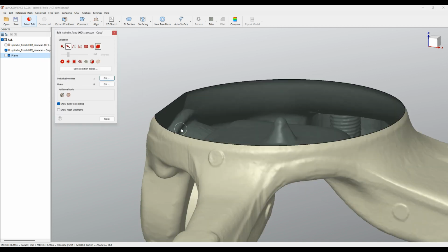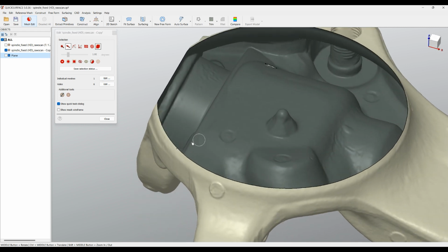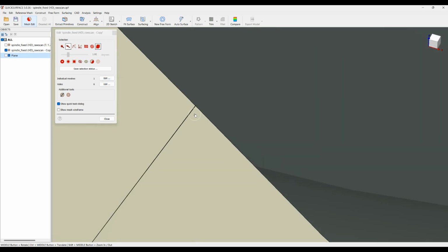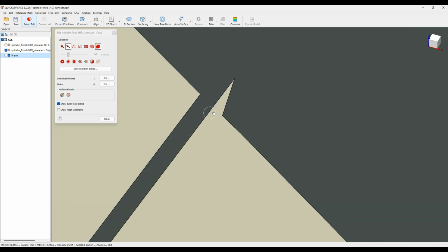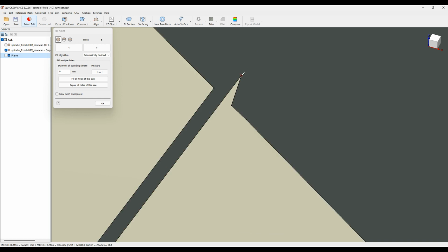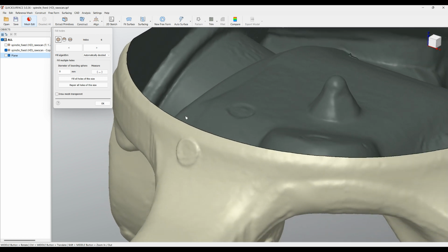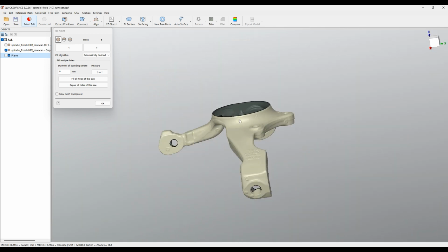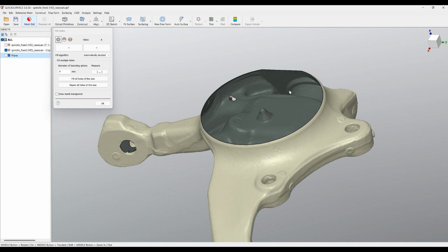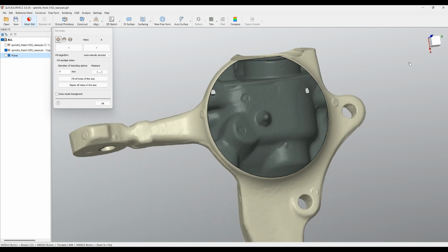Let's press OK. Now I can see the areas which are problematic, and I can probably need to just repair a little bit here by edit and closing this area here, because automatic surfacing needs really nice good boundaries. So you can see that I opened this hole here. I will carry on and we'll place in top view.